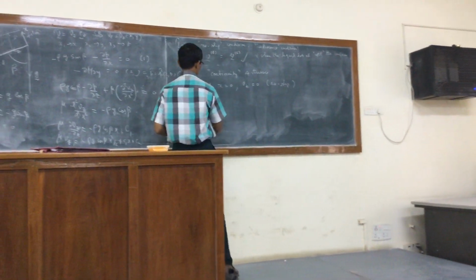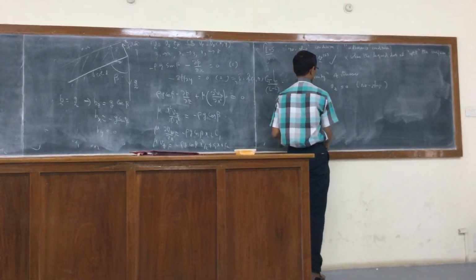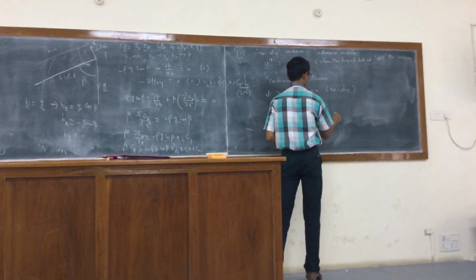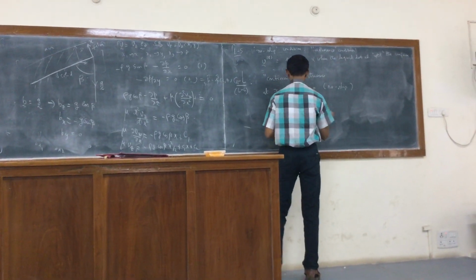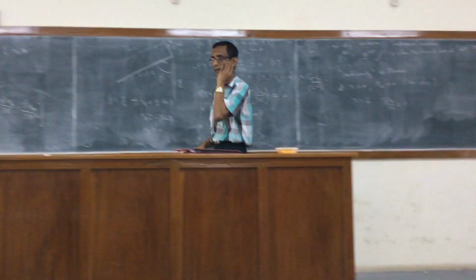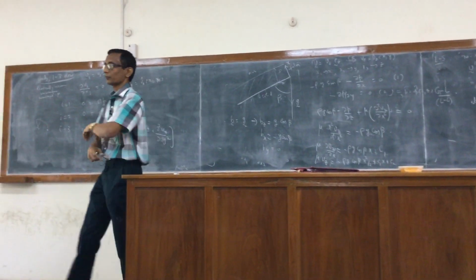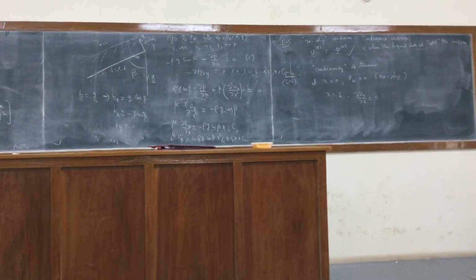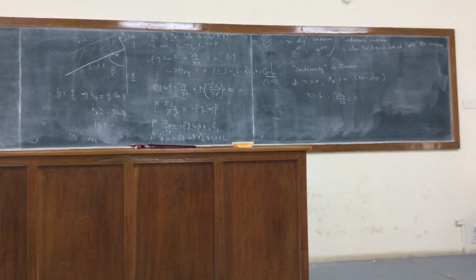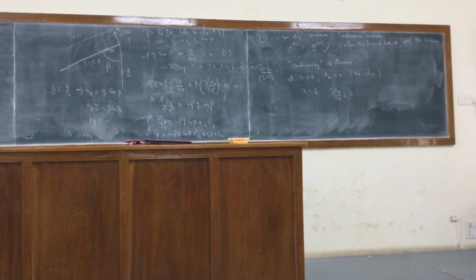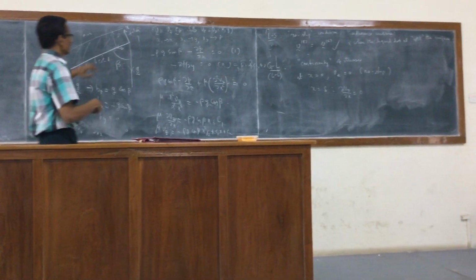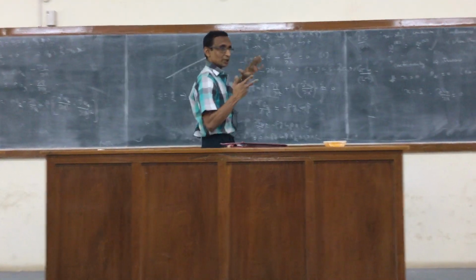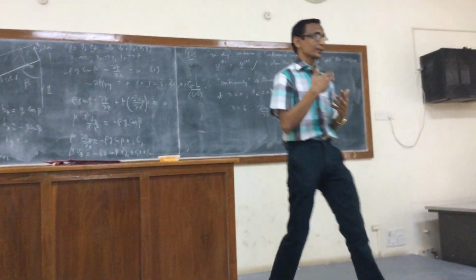Now the continuity of stresses would mean that at x equal to delta, dv_z by dx is equal to 0, right? At the interface between the gas and the liquid. So now we conclude that the continuity of stresses would mean this. Shear stress is very low at that. Yeah, shear stress. In fact, we have to look at now how the stress picture would look like, both within the liquid and at the interface.